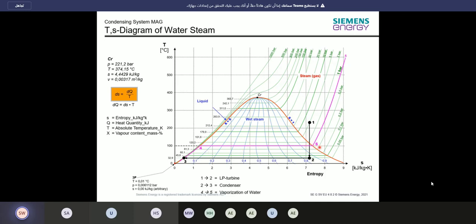In the evaporator on the power plant, it can be that you're getting water out with 90%, in some startup cases 80%. And these will be separated then inside the drum. But the temperature will still be saturation temperature in there. So there will be no cool down to somewhere over here where we'd say we have steam now with 70 degrees or something. This does not happen. It happens all over here, vaporizing at the same temperature.